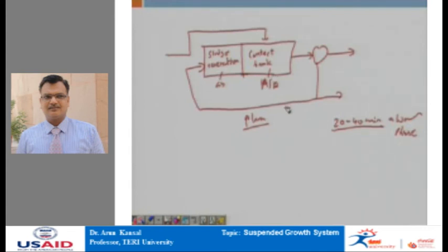The settled wastewater is mixed with the re-aerated activated sludge and aerated in the contact tank for about 30 to 40 minutes. During this period, organics are absorbed by the sludge flocks, and the sludge is then separated from the treated effluent by sedimentation and returned into the sludge re-aeration tank, where it is aerated for 3 to 6 hours.